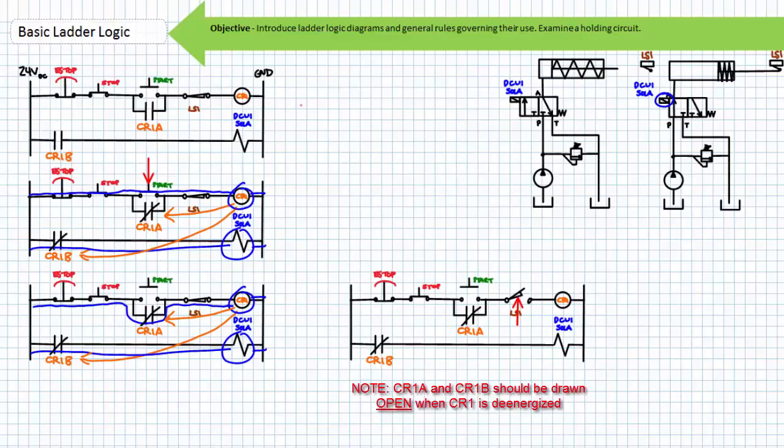If at any time an operator wanted to stop the cycle mid-stroke and retract the cylinder, they can press the momentary stop button. This returns the system to its go state, ready to initiate another extension. The e-stop, in contrast, would be for dangerous situations, necessitating not only a stop mid-stroke and retraction, but also a complete disabling of the system until such time the e-stop is reset. Let's walk through the ladder logic together and illustrate the function of this one-cycle reciprocation system.